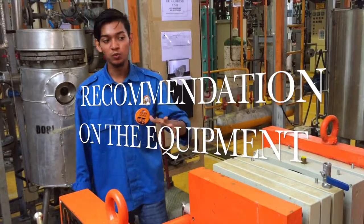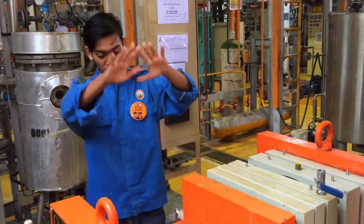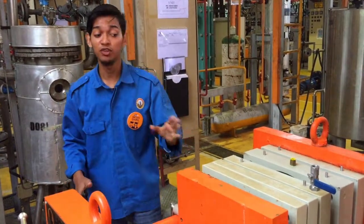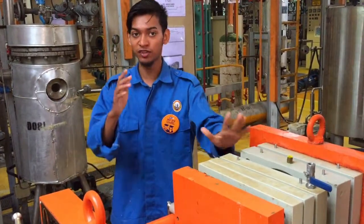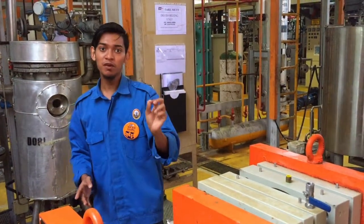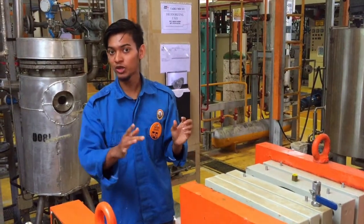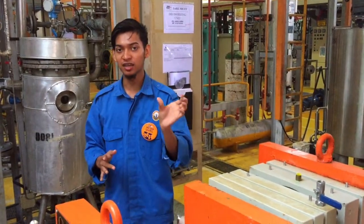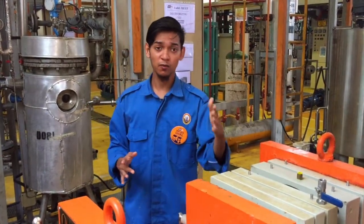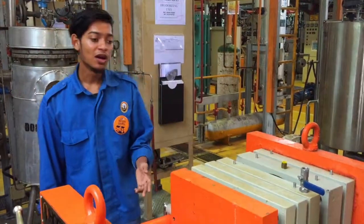Okay, the method to prevent the equipment from damage is, firstly, we should clean all this filter press thoroughly after being used, and then we should power wash the plates and the filter cloth to avoid cake build-up in them. And then if we pump low solid, we should avoid pumping low solid at a fast rate, because it will speed up the wear out of the closed plate and the pipelines.